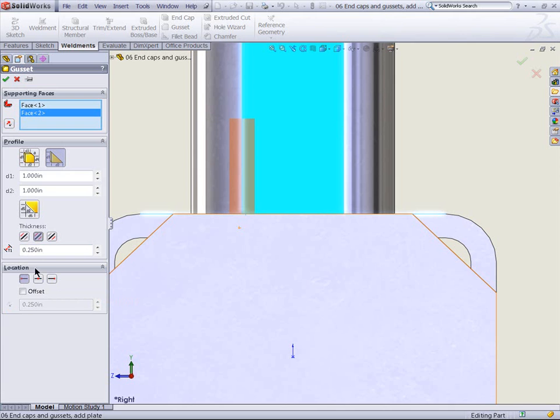Now, if that wasn't enough, just turn on the offset and then specify how much to offset the gusset from. So in this case, I'm offset 1/4 inch from the midpoint based on the exact middle of my gusset. Again, I could specify where that offset is coming from. Here it'd be from the inner side. Although a little strange on how to position this, this will give you exactly what you need.